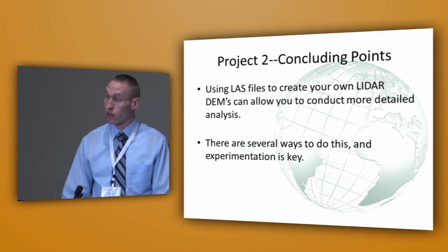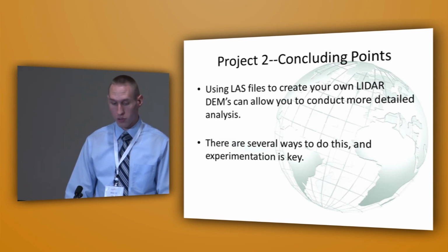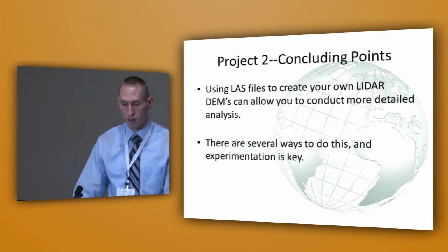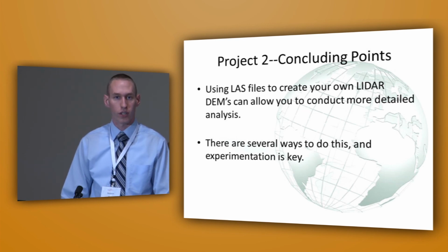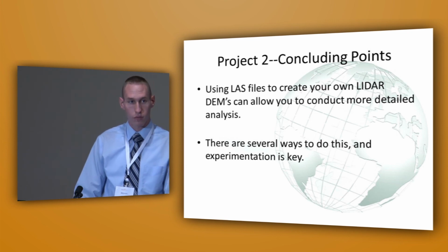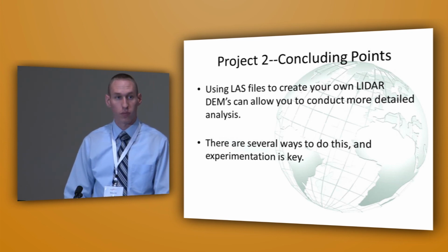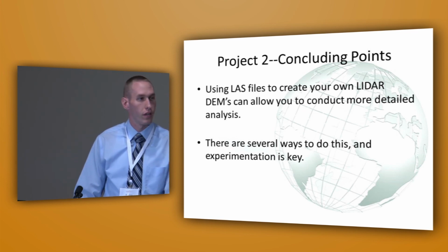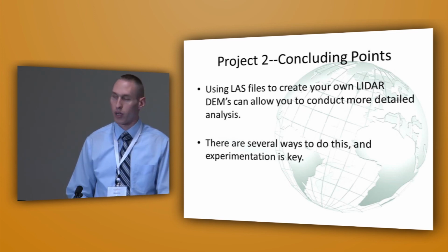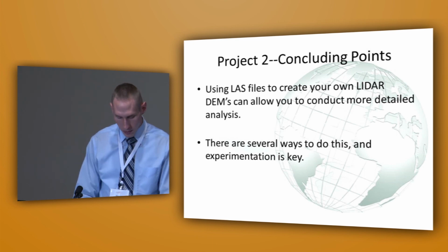So the thing that I learned during this project was that sometimes using LAS files to create your own LiDAR DEMs can allow you to conduct more detailed analysis, as opposed to downloading the standard USGS DEMs from their website or anywhere else that you like to download DEMs. There are several ways to do this, but experimentation is key. I've found a lot of times in my experience with GIS, there are multiple ways to do one thing. And if you play around with the software a little bit, sometimes you'll be able to find better and better ways to do the same thing.